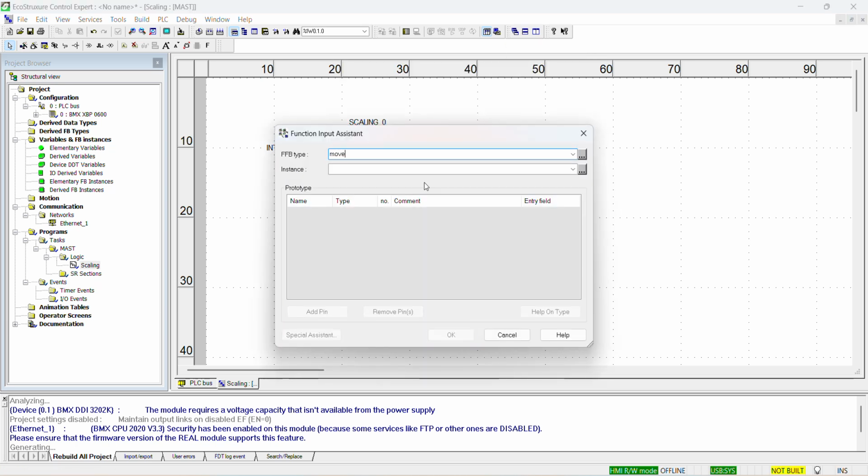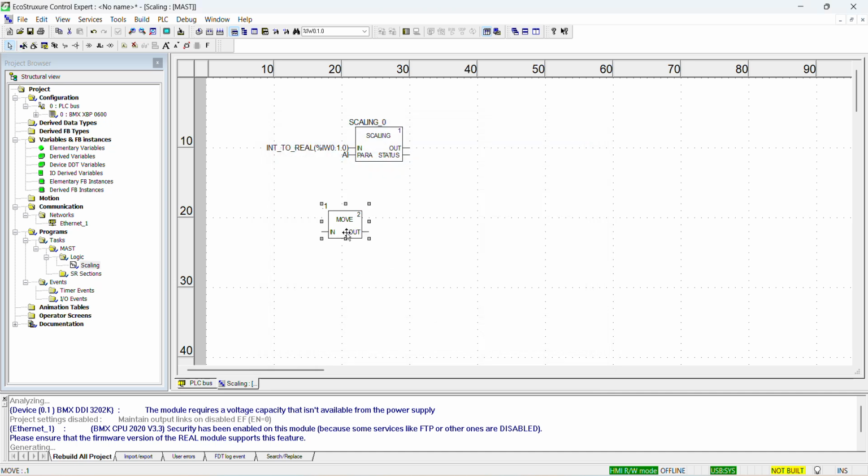Here I'll write move. Click here, this is my move. So input I'll consider 0 as 0. In default Schneider Electric input you have to consider 0 to 10,000 counts. You'll get a raw value, it is 0 to 10,000. So similarly copy paste and this will become my 10,000. Unlock input, copy, paste here. Suppose you have a temperature sensor 0 to 250 degrees Celsius, then I'll write this is the maximum.